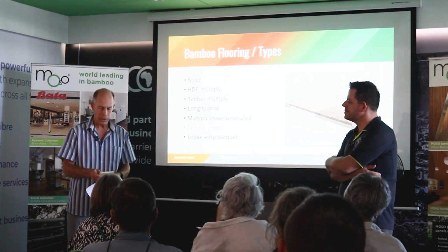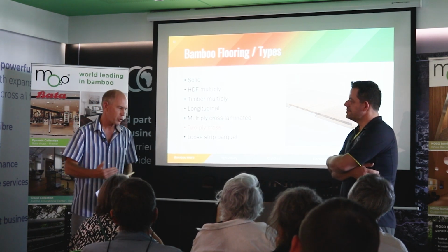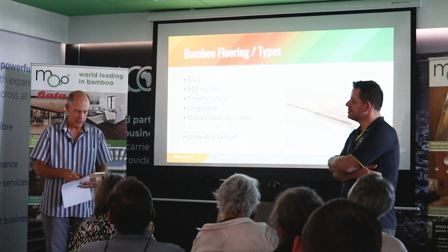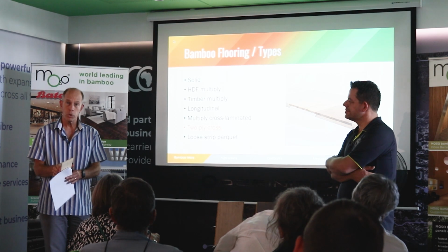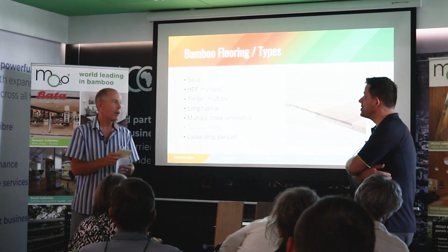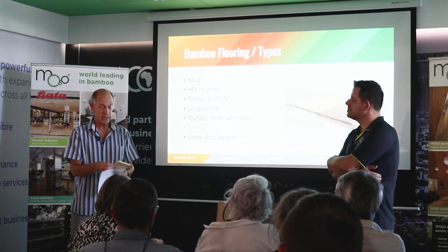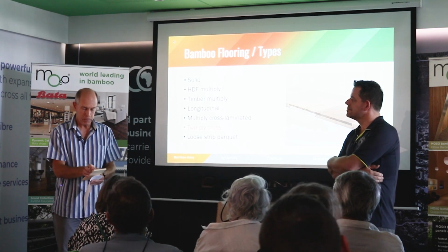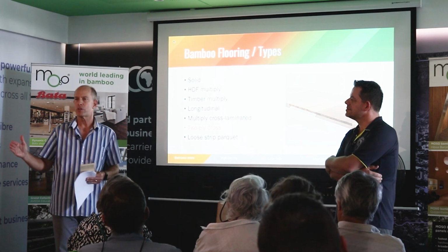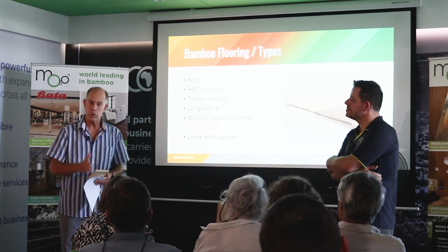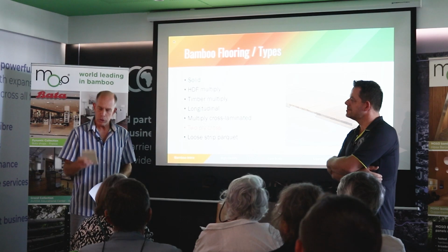Being only two-ply, being quite thin, being quite small planks, again, it's a lower cost option than some of the thicker, wider boards. But being cross-laminated and glue down, being relatively small planks and tongue and groove only. Great acoustics. Small planks mean the tongue and groove connection means that expansion and contraction is taken up within each board, and therefore you can do very large surfaces, very large floors with no expansion joints. So this is a very good commercial floor.